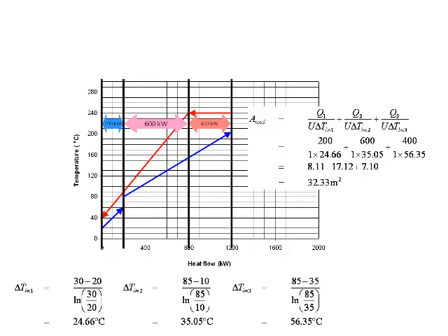Having achieved 600 kilowatts of heat recovery using quite a large heat exchanger, look at that, 17.12 meters squared, we've now reduced our cooling water requirement all the way down to 200 kilowatts and our steam requirement down to 400 kilowatts.